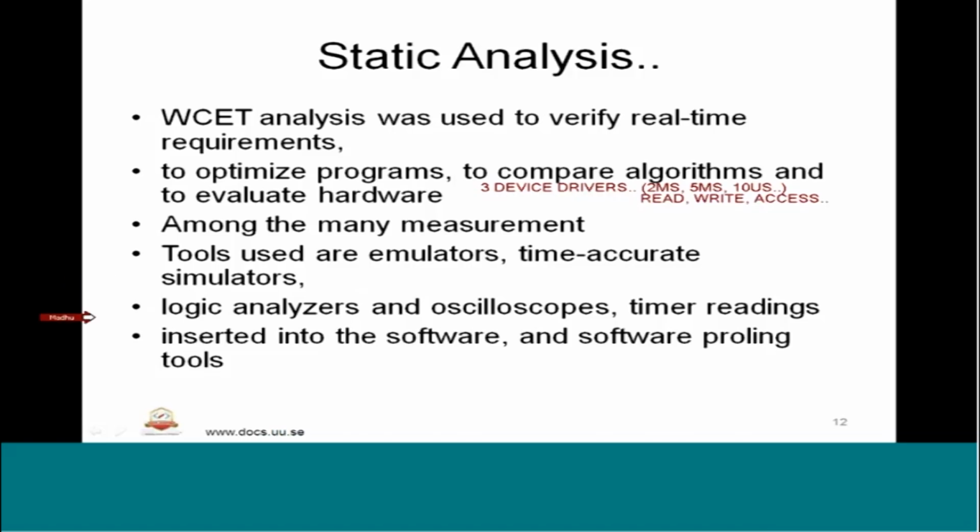Then we have logic analyzers which can be hooked into the embedded software, and with the help of logic analyzers timing analysis can be done. And we use oscilloscopes to measure the various timing aspects. We know that an oscilloscope will help in doing the plotting. So we have something like this, and we can measure time like this, or any waves in the oscilloscope,